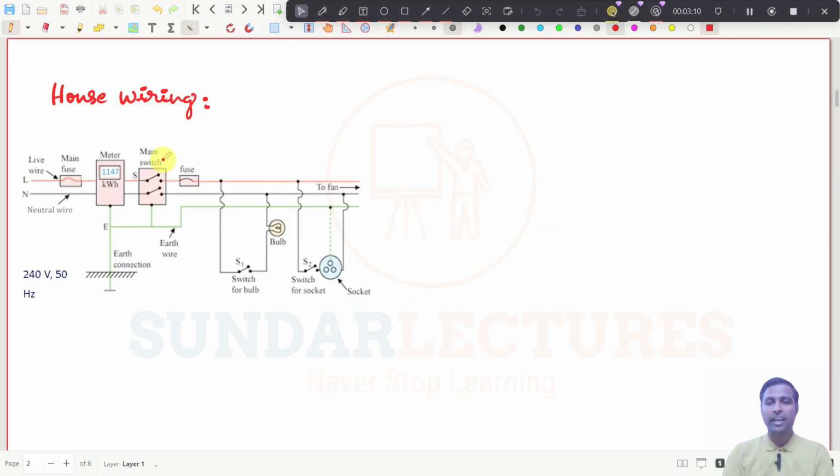See, we will take an example like this. This is actually a house wiring, where we connect a line and a neutral, which means a phase and a neutral. We will connect a fuse, and we will have a meter to read energy, and a main switch, fuse, and then we will connect the bulb like this. From the phase, you take a wire and put a switch, and then it is connected to the bulb, and neutral is directly connected to the bulb.